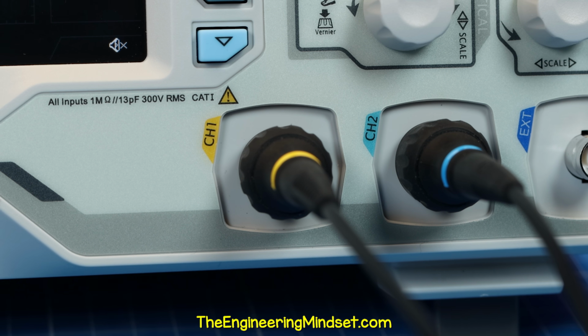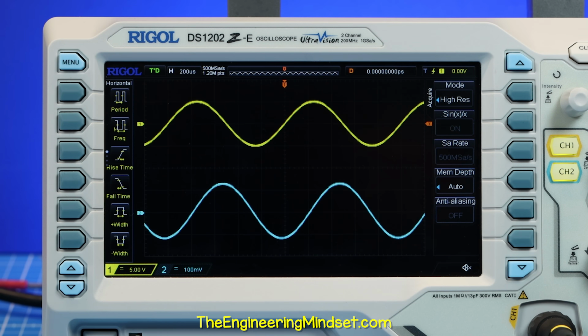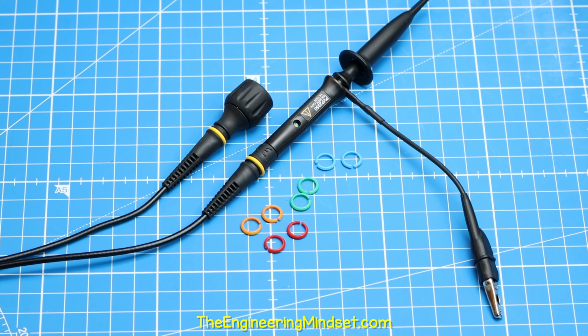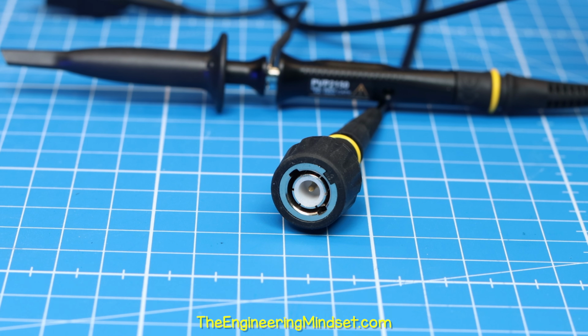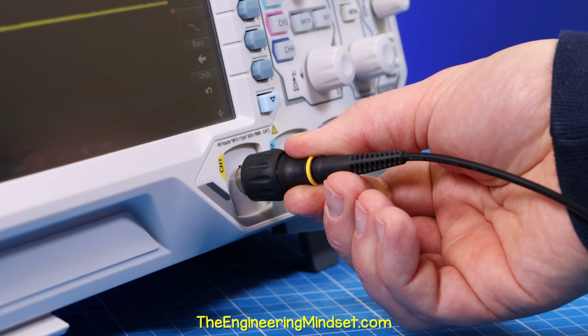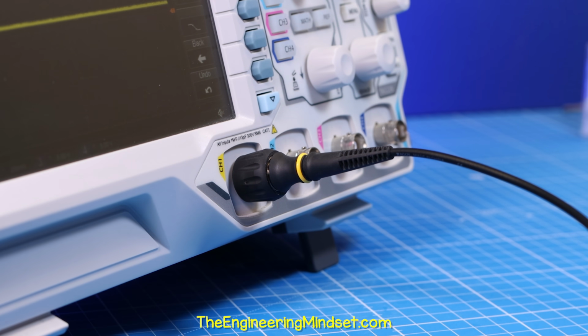The channel terminals are usually color-coded, which match the signal profile on the screen. And you can also clip corresponding color tags onto the probes. The channels use BNC sockets, and the probes use BNC connectors. For channel 1, gently push and rotate the connector until it slides on. Then slowly rotate it to lock it into place.